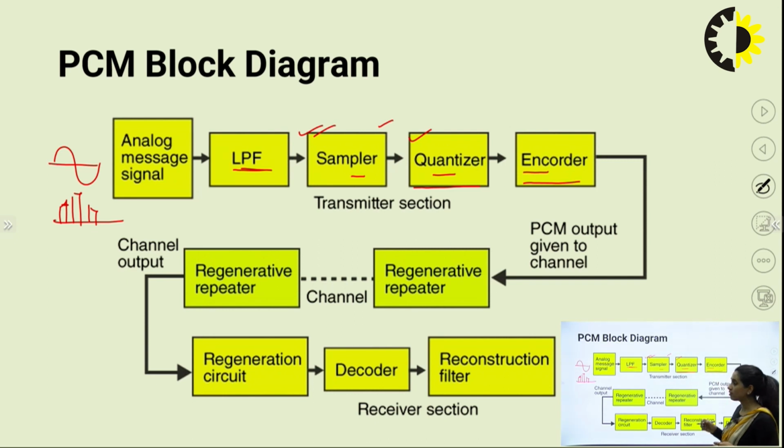Now what travels on air is my binary bits. So I have successfully generated binary bits. Now, if the channel provided to me is wired in mode, then simply my bits won't travel. I have to transmit some voltage levels, right? So in case of pulse code modulation, my analog signal is encoded as a series of pulses, and that will be propagating via the channel.